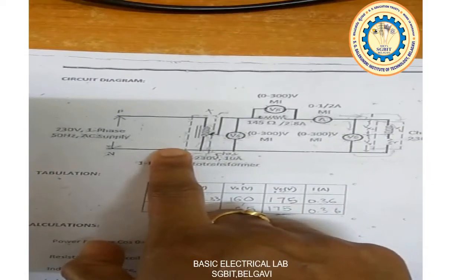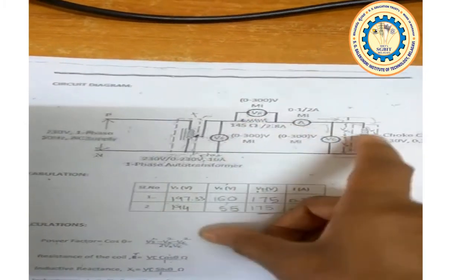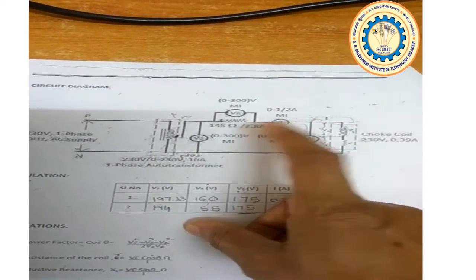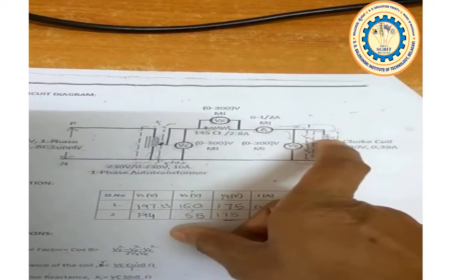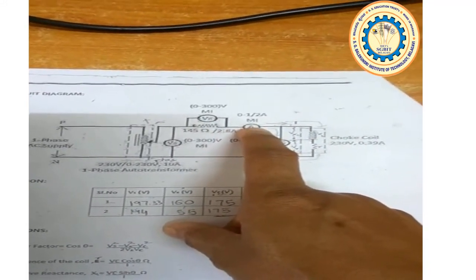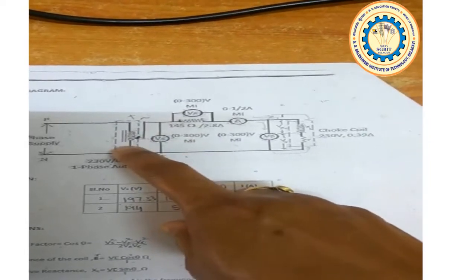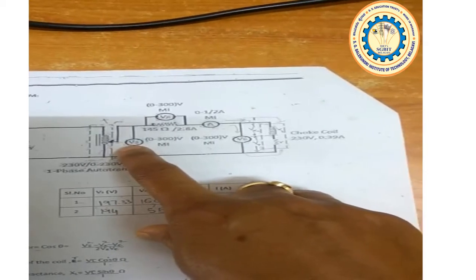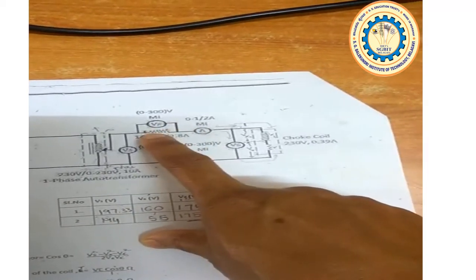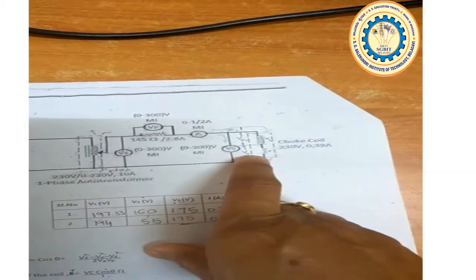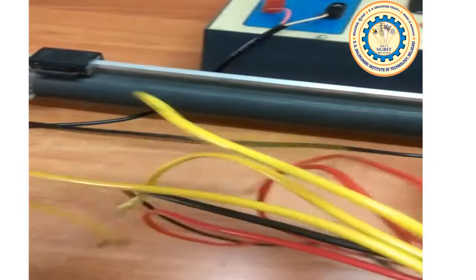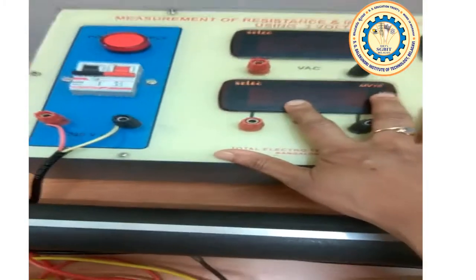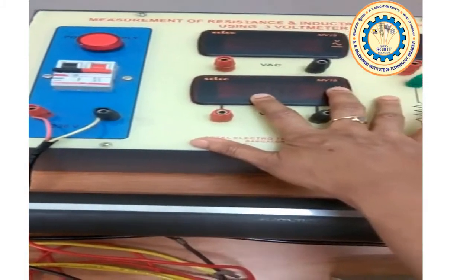This is the circuit diagram, and in the circuit diagram we have an auto transformer, then the rheostat, then the choke coil. The choke coil and rheostat are connected in series with the ammeter, and this is connected in series with the auto transformer. The 3 voltmeters are connected across the supply, that is the auto transformer, and across the rheostat and across the choke. So here these are the connecting wires, and this is the kit which is used for this experiment,